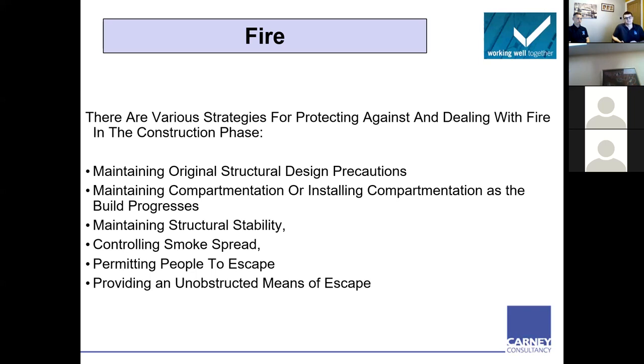Big thing with fire is anyone sleeping in there? If it's a refurbishment project, someone's going to be sleeping in that. It's a hotel, a sheltered accommodation. You need to think long and hard about your controls for maintaining the compartmentation, maintaining the means of alarm, and maintaining the evacuation, because again, it's critically important.